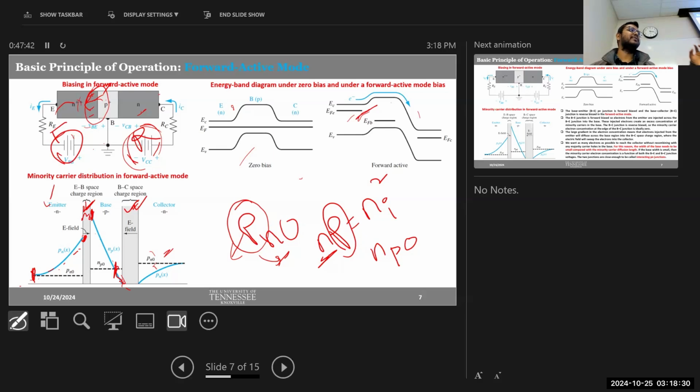The electron is flowing from the emitter through the base. It is going to the collector. Now, when more electrons come, they will replace the holes in this depletion region, right? So it will first replace the holes from the depletion region, and then it will keep traveling. So if we look at the closest point of the depletion region, here we will have the lowest number of holes in the collector because electrons are coming and they are replacing holes, right?